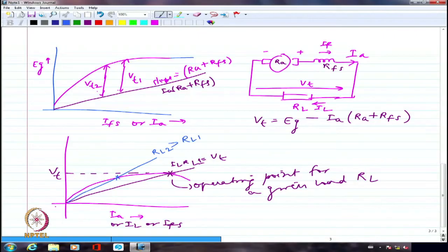What he is asking is, if the voltage is shown to be flat, saturation has been attained, then after that it should start dropping right away, because if the voltage is a constant, the IA-RA drop is continuously increasing as my IA is increasing. So you should not have any flat portion at all. It should start dropping right away. What he means is, I should have drawn the characteristics increasing, and after that it should start dropping. Hardly ever should there be a flat portion in the series generator.